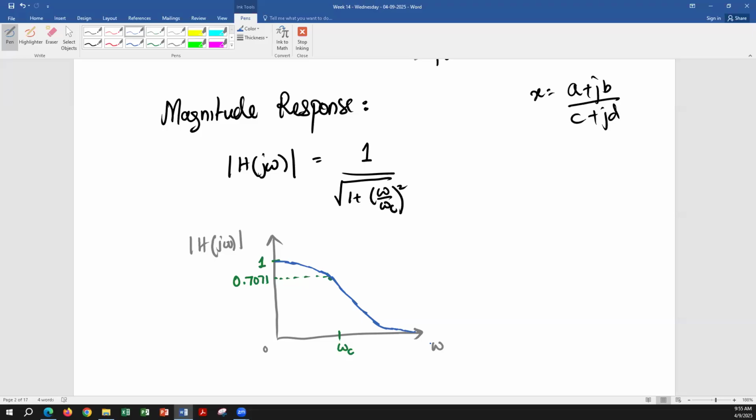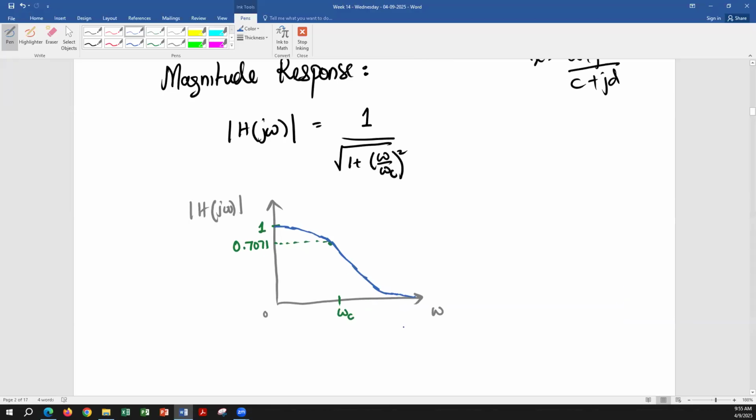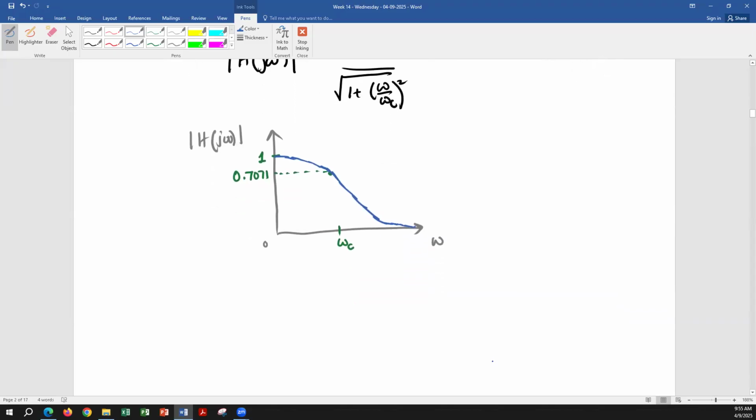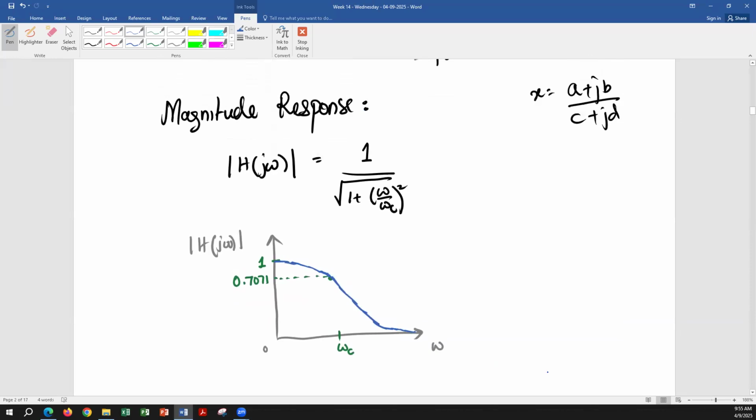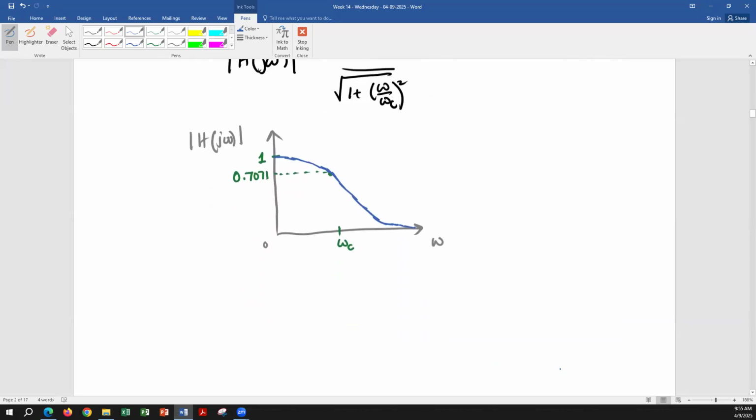And in AC sweep analysis, it's going to give you two options: linear or logarithmic. Most of the time, we choose logarithmic. That will change the x-axis into logarithmic scale, and you can see the filter response very clearly, like this type of response. Okay, and again, we're going to plot it in MATLAB, and then you're going to simulate it in PSpice as well. So this is the magnitude response. As far as the phase response is concerned, now who is going to tell me again?